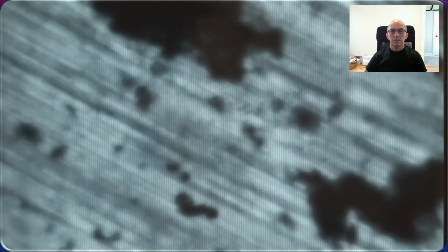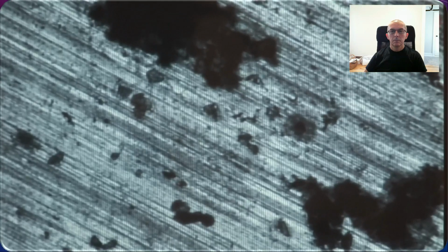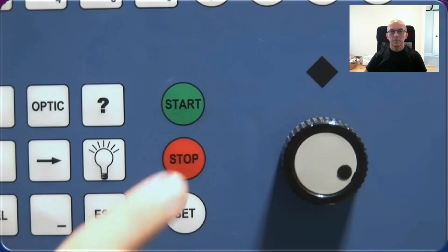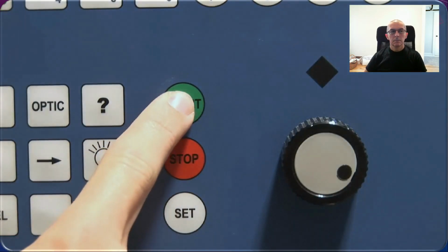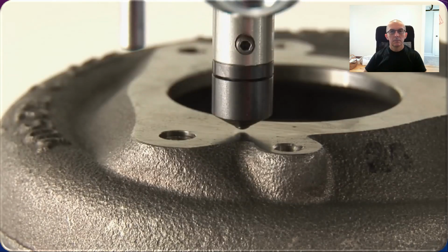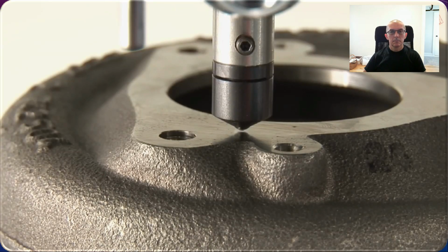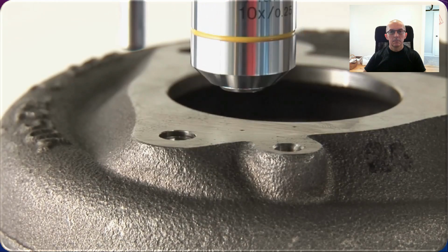After bringing the test piece surface into focus, he selects the exact spot where the hardness test is to be made. By pushing the start button, the hardness test procedure begins. The testing machine rotates the lens back to its resting position and places the spherical indenter carefully on the test piece surface. Gradually and shock-free, the test force rises to its specified value. After maintaining the test force for a certain time, the indenter automatically lifts off again and the microscope lens pans back to its former position.